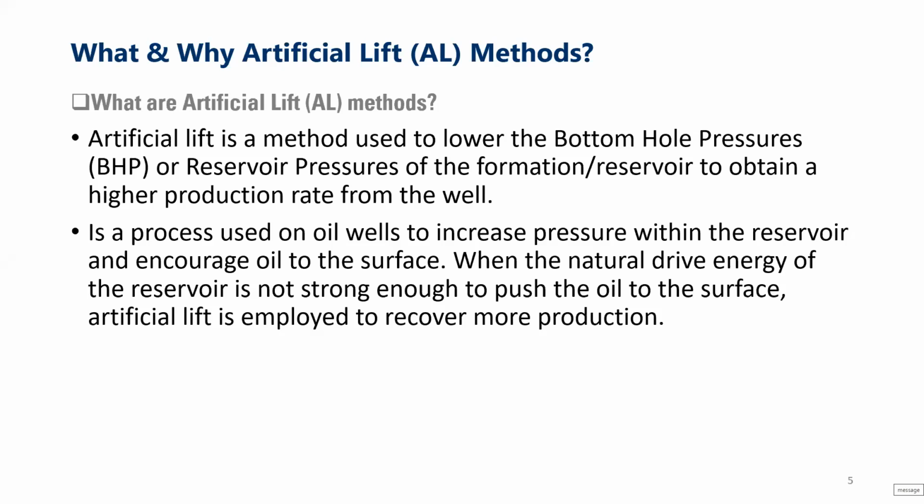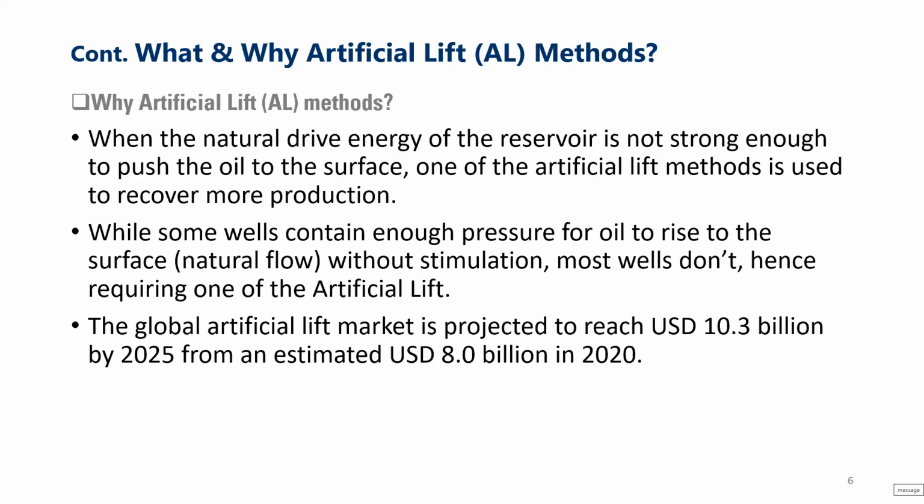So this lets us emphasize that we might need an artificial lift method right from the beginning, if we obtain from the readings and parameters that the pressure is not enough to come to the surface. Secondly, we might need artificial lift after some time, once we have exhausted the pressure and the well has been flowing naturally for a couple of years or so, and then the pressure depletes, and then we will need an artificial lift method. Which artificial lift method is useful, we will find in the next slide. But for now, this is the introduction to what artificial lift methods are and why we need them.